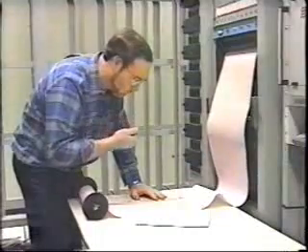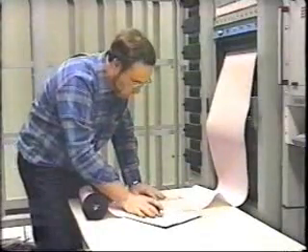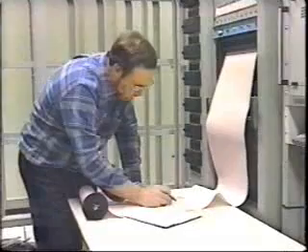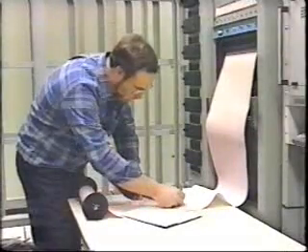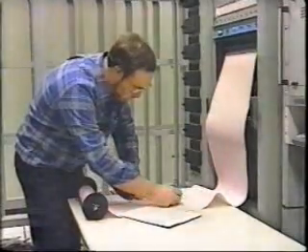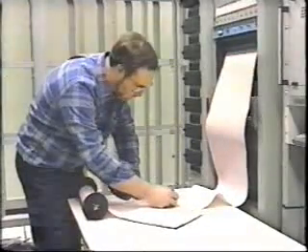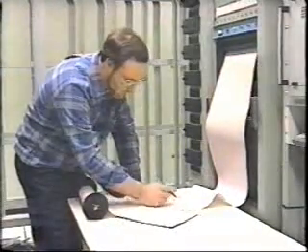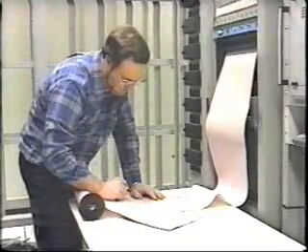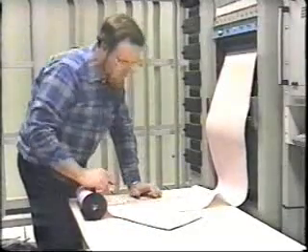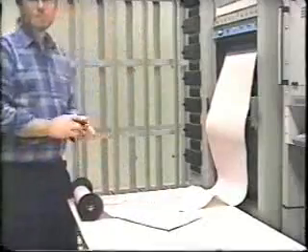In this particular case, the investigator, using all of the data along with the oscillograph traces, decided that all relay and breaker actions were correct. This is noted on the form. Any misoperations would typically be reported on a separate log and a thorough investigation would follow. Of course, these relay action reporting procedures will vary from utility to utility, so you must be sure to check and learn your own company procedures.